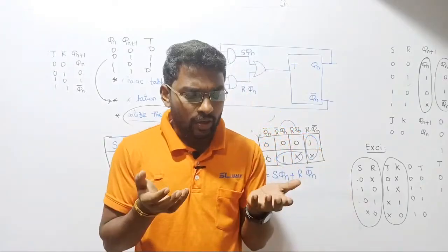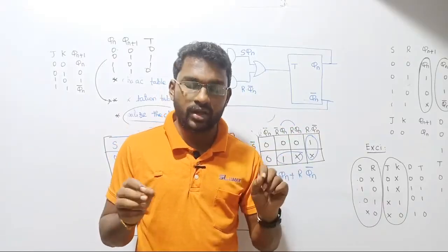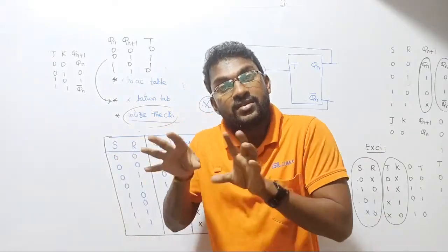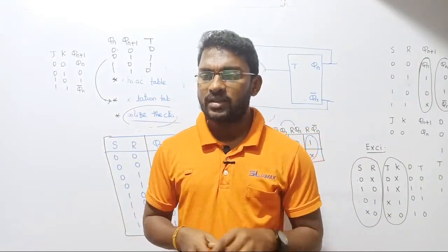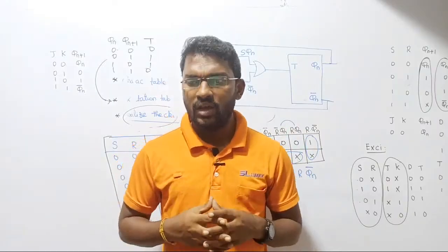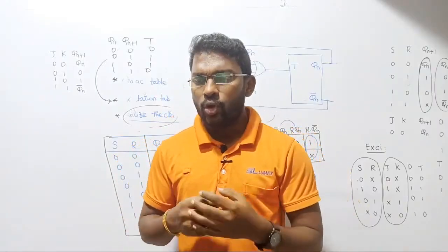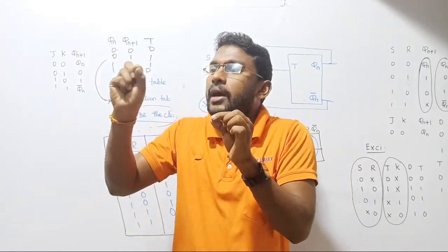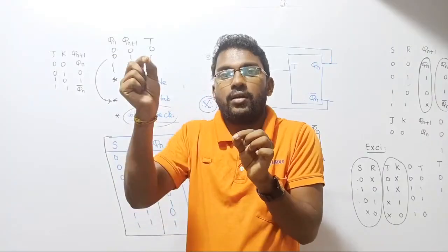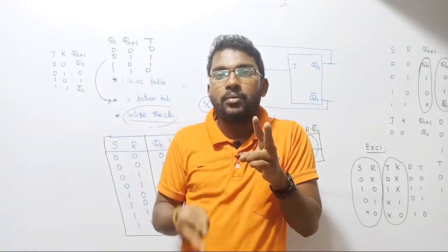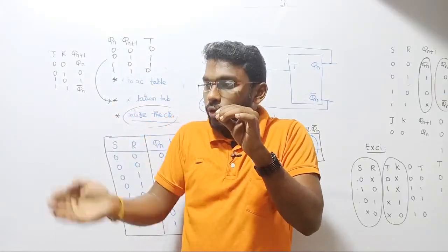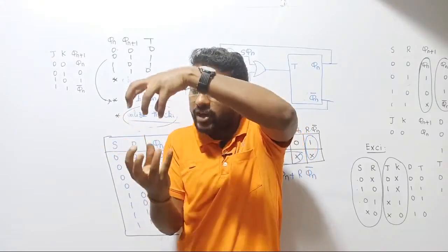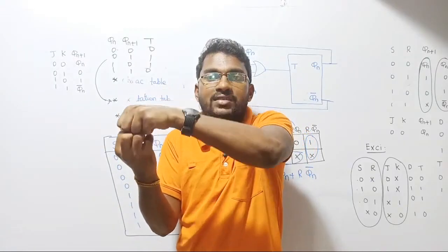So what is the difference between synchronous machine and asynchronous machine? Why is your synchronous machine called synchronous machine? In a three-phase synchronous machine, we are considering two types of rotation. One is the rotating speed of the rotor, as well as the rotating magnetic field, the revolving field. So there are two things revolving inside the machine, our rotor and our rotating magnetic field. They rotate at the same speed. They are synchronizing together. That is called a synchronous machine.